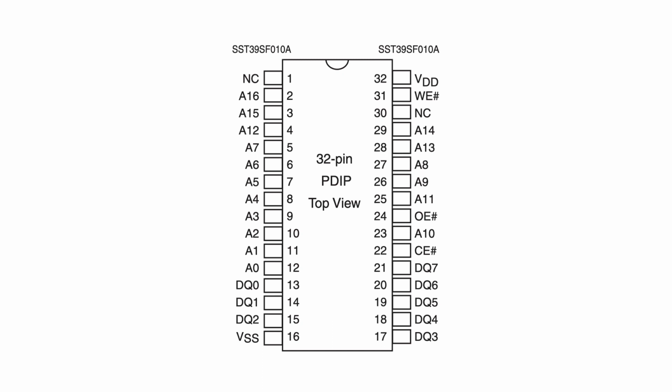This chip has an asynchronous interface that expects a strobe on the input corresponding to the type of transaction, a read or a write, that's being performed. The AT28C64E PROM that'll be used for the fixed ROM, and the SRAM chips that'll be used in the various banked RAM regions of the machine, have the same requirements. So I'm going to need to add some logic to generate these strobe signals.